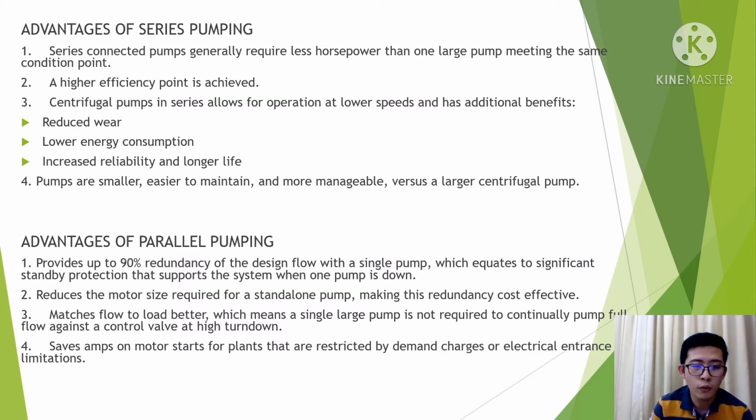It matches flow to load better, which means a single large pump is not required to continually pump full flow against a control valve at high turndown. And lastly, it saves amps on motor starts for plants. They are restricted by demand charges or electrical entrance limitations.